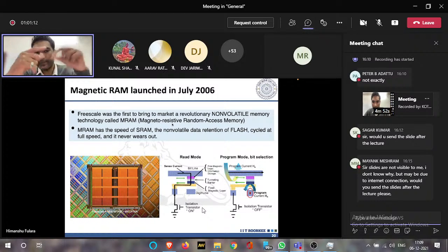The effect is quite similar to giant magnetoresistance: here also one type of spins experiences a large scattering while tunneling through this spacer layer, and the other spin configuration experiences less resistance to the tunneling of the electrons. So one spin can tunnel very easily through this structure, and the other cannot.